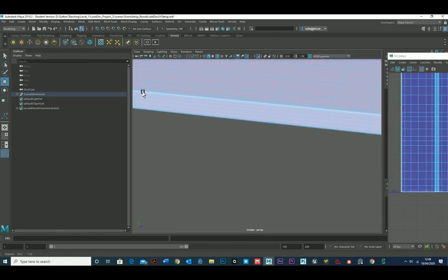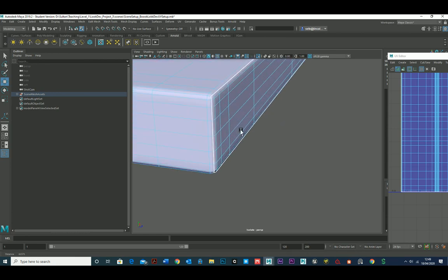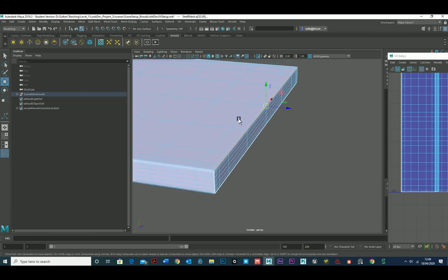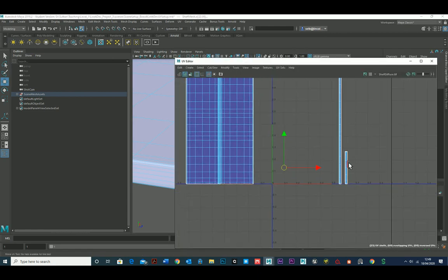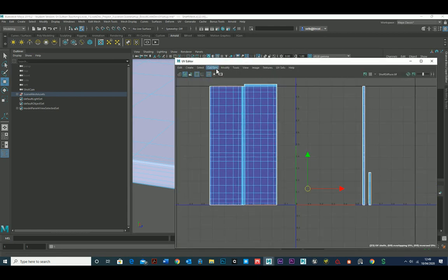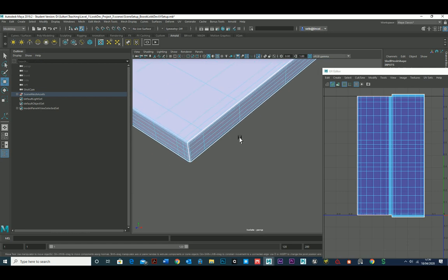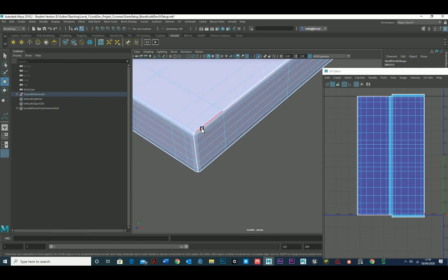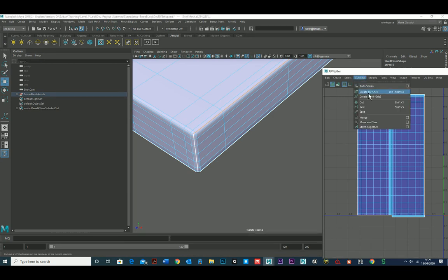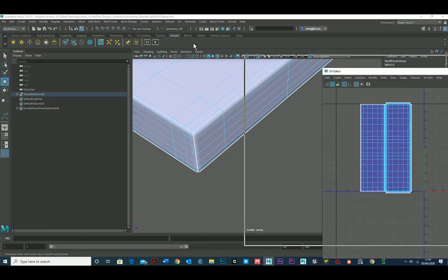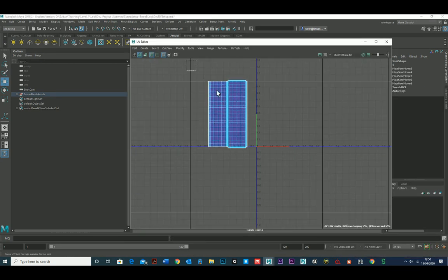The same thing for this part. Double click, that border edge is selected there, and we're looking for its neighbor, which is that small piece. Cut and sew, move and sew. And there is this extra piece left, which is this back side. Again, because we might have shots where we're always going to see the top of the shelf, it's better to stitch that as well. And that's it. So that's our UV atlas for that